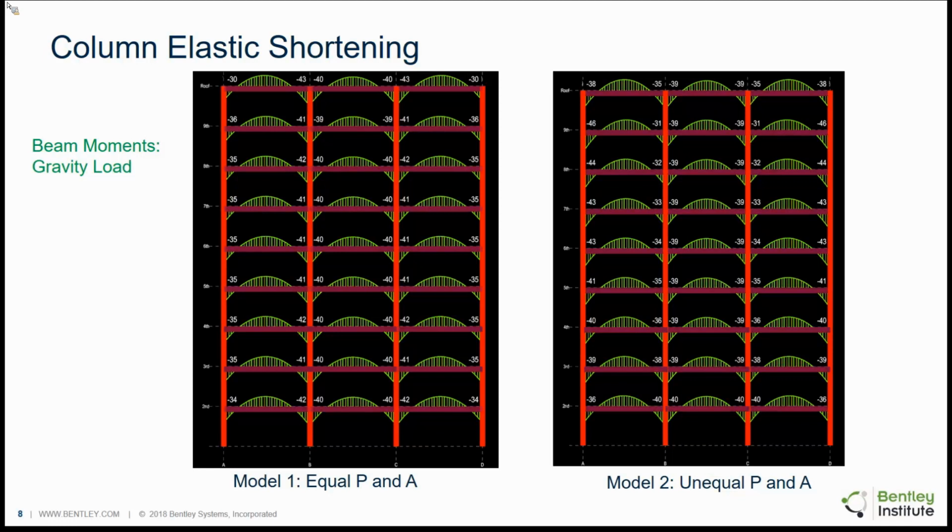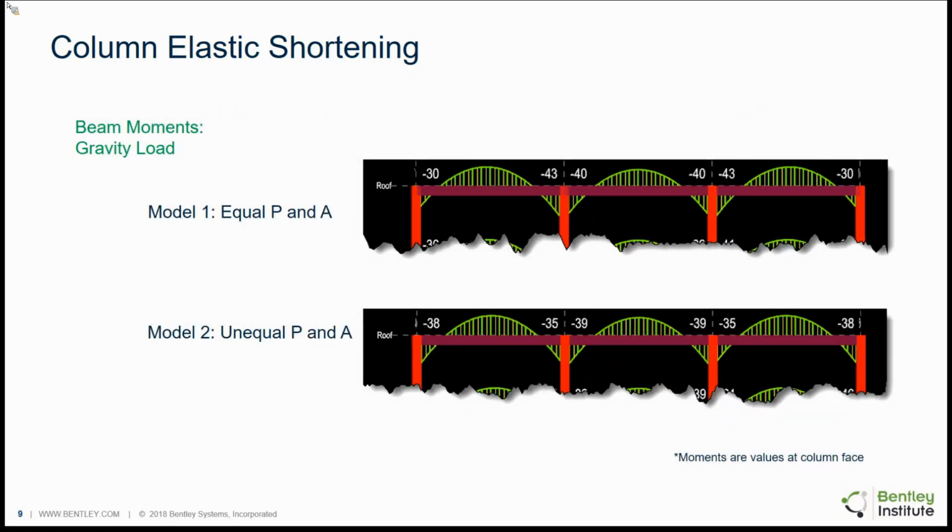And if you'll note, at the lower levels, there's not as much difference, but as you get towards the top, the differences tend to get greater. And so I've grabbed the top set of moment diagrams from those two models so that you can more clearly make the comparison. Notice in the midspan, there's not a whole lot of difference, but it's those end spans that are particularly impacted.